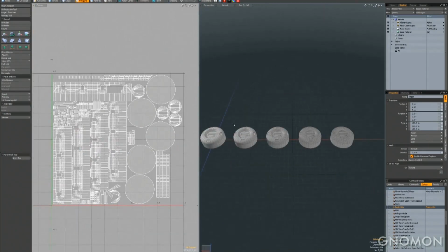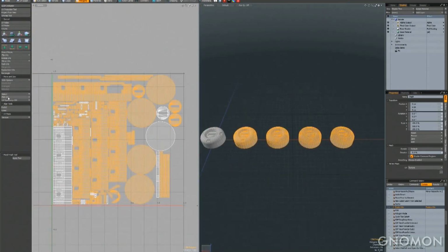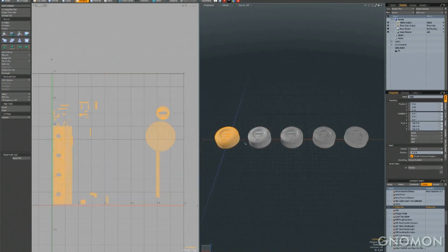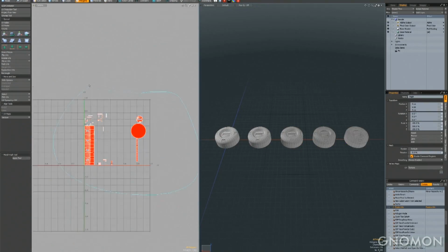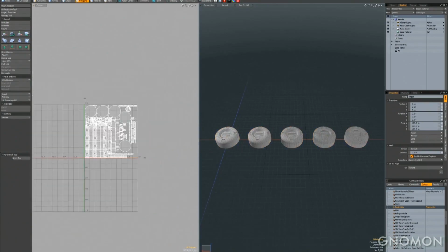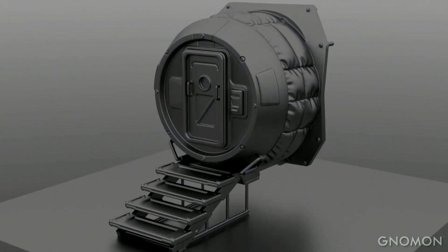And right here, I've made a separate macro that will take geometry underneath whatever my cursor is hovering over and copy it without even clicking. Then I'll hover my mouse over another piece of geometry, and without clicking again, I'll press my hotkey, and it will duplicate and propagate those UVs across different pieces of geometry. That's super useful when you're doing stuff like modular building for games, when you've got UVs that you're going to propagate across a high poly mesh or something. So let's see how you bake that stuff down.